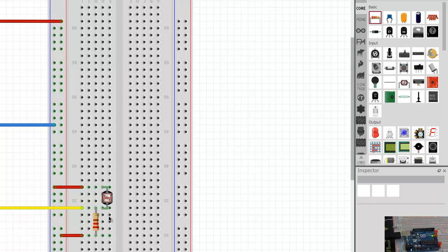Now, please keep this in mind. No two LDRs will be the same. They will not have the exact same value, and maybe they will have different coefficients. One of them might be positive, one of them might be negative. So an LDR is usually used for detecting either 0 or 1 levels, when you have a high threshold and you don't care about any rubbish data. But using an LDR to sense light intensity is not a good idea. Use something like a photodiode or anything electronic. Don't use an LDR. Just an advice.